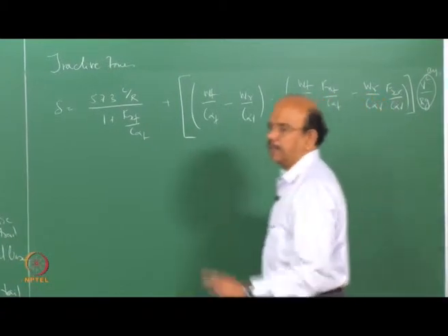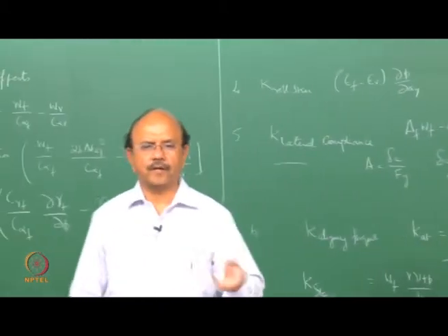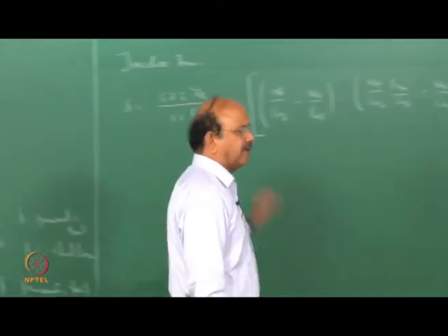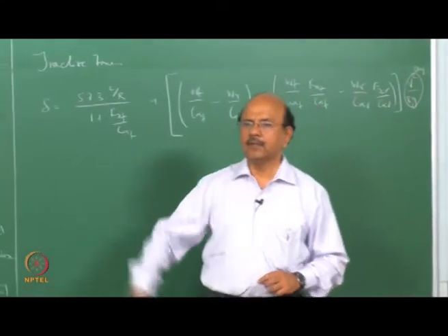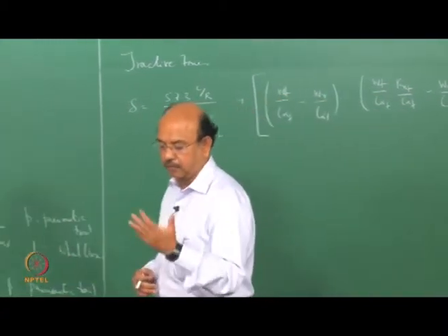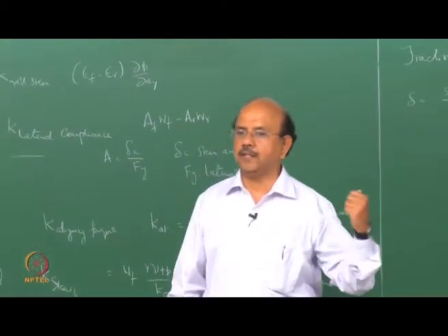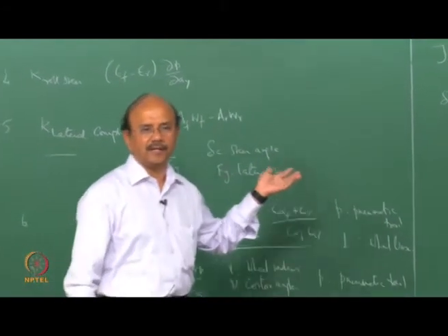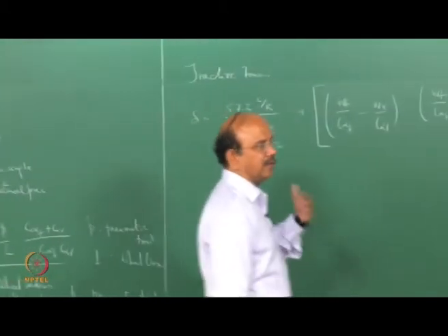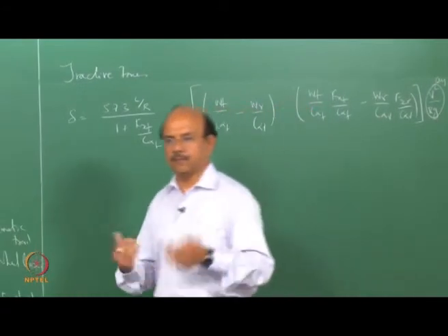And lastly, there are two things which we have left out. One is the load transfer to the front because of acceleration, deceleration, and so on. We mentioned that. We have not taken that into account like what we had done for the rear and front due to roll. Here this is due to pitch. Unfortunately, the model which we have won't be able to take that into account. So you have to go to a much more detailed model if you have to look at how load transfer is going to have an effect on this.